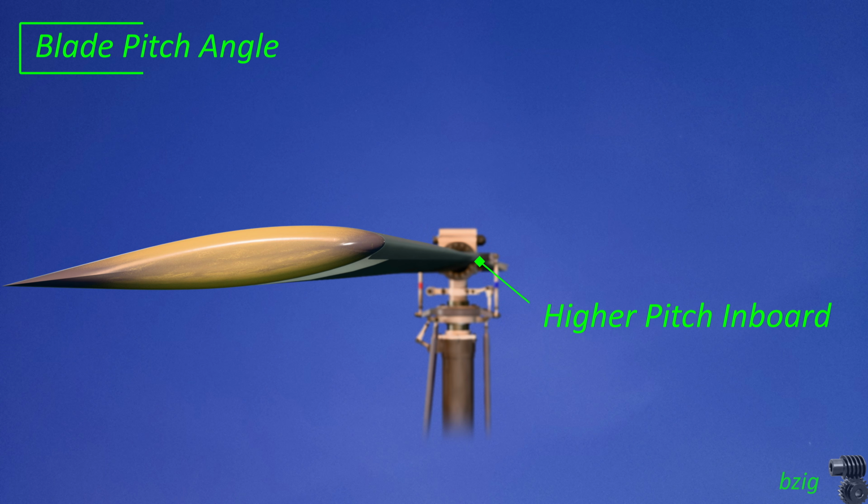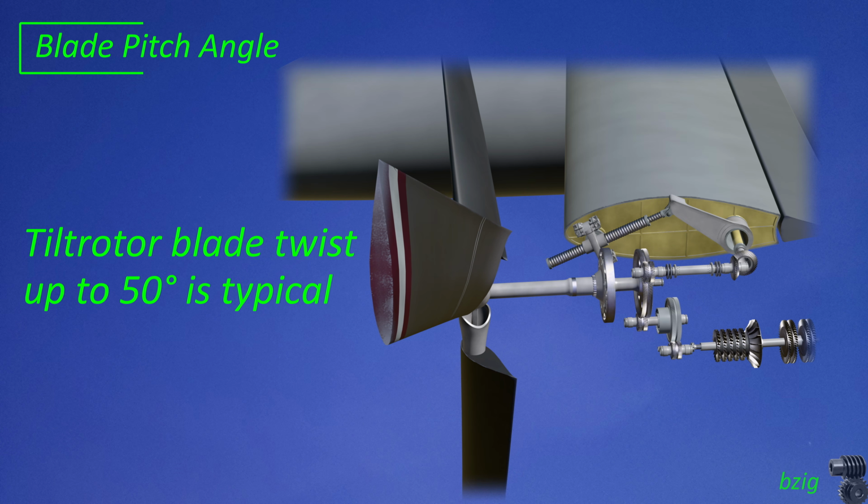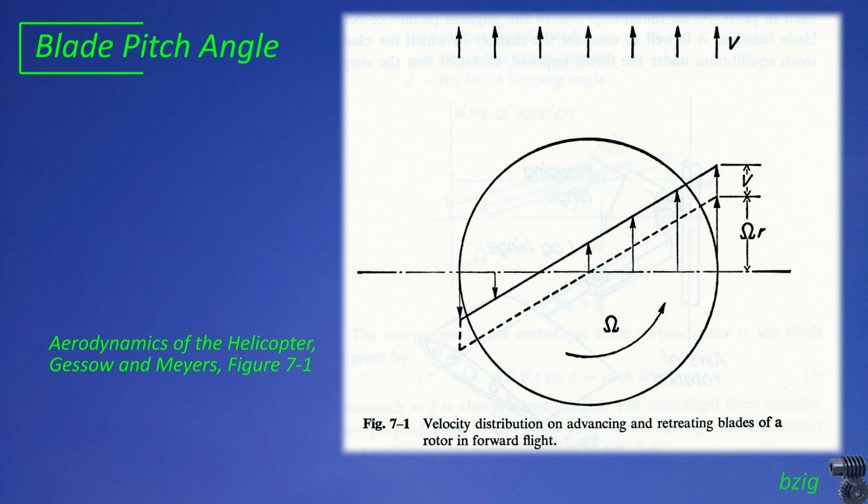Almost all helicopter blades are twisted, with a root pitch angle greater than the tip. Typical values of twist range from 6 to 18 degrees for helicopters and up to 50 degrees for tilt rotors. The reason for twist in rotor blades is an attempt to account for the change in the tangential velocity that we just talked about.